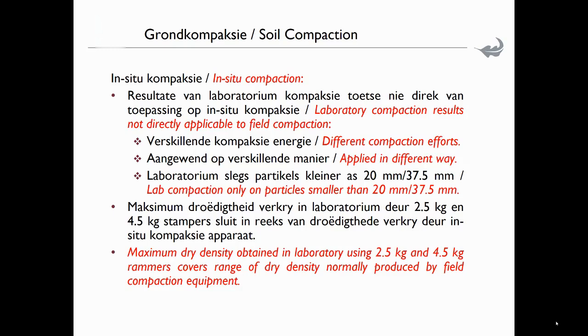In situ compaction, what we're saying here, this is the compaction we're doing while we're in the field. So what you see while you're driving along the roads and construction sites and road works, for instance, the work that Martin and East has been doing for ages near the Somerset West Mall, you probably have seen a lot of these compaction instruments or machines. And the reason why we have to look at it is because the laboratory compaction results are not directly applicable to field compaction.